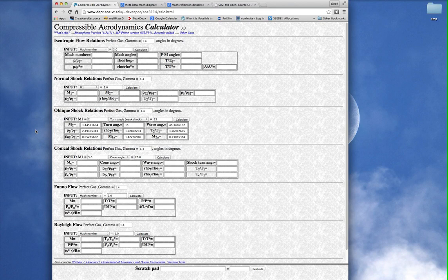In this tutorial, what we're going to do is do a quick CFD simulation of an oblique shockwave over a wedge. The wedge angle will be 15 degrees and a Mach inflow around Mach 2. What we're going to do is first build the grid, and then we'll have a little time while it's running.